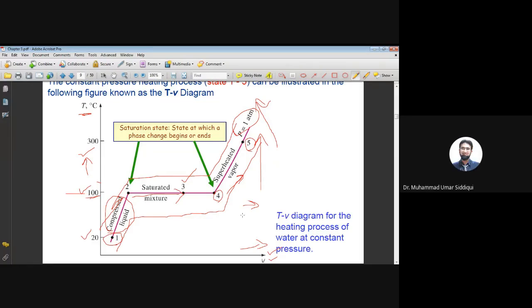No, the thing is that if you make it a closed system, you need to understand the physics and the chemistry behind it. Vapors are being generated, vapor needs more space, but you are closing the system, so you are not allowing the vapor to escape. So what will happen? The pressure will increase, right? So when the pressure increases, this is going to suppress the boiling process.